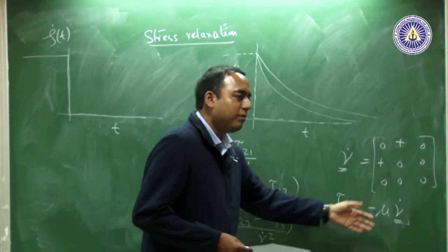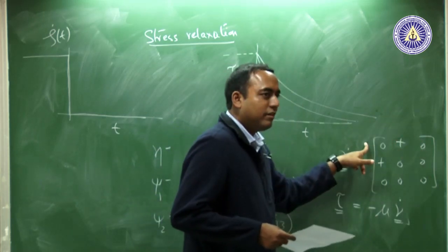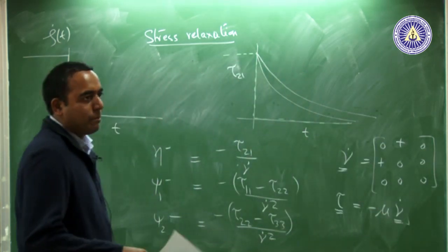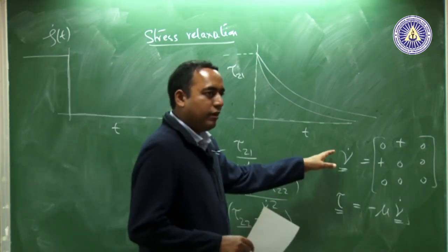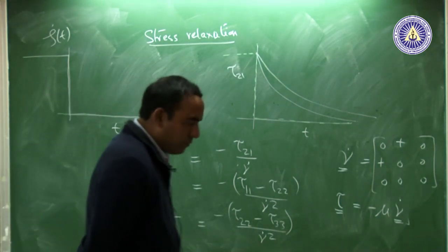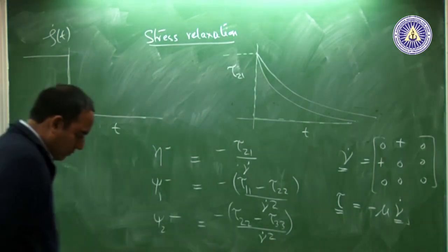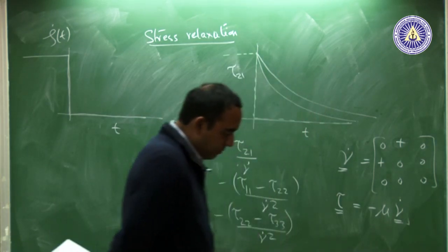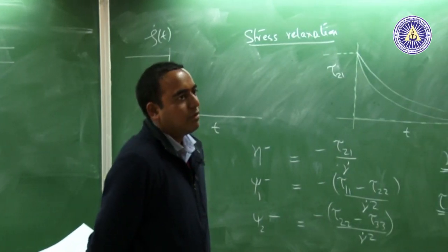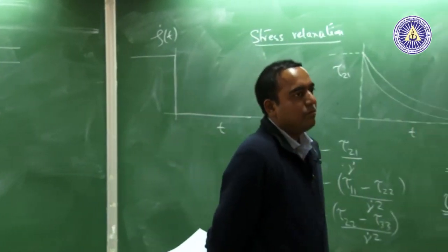See, in Newtonian fluid mechanics, this is the constitutive model that you have, which says that the stress generated is simply proportional to this matrix. But what if it is not simply proportional? So, is it still a function of that matrix? It will be, it has to be. What I am saying is that in these equations I do not distinguish between the 1 and 2 directions, E1 and E2. So, this is a function of this matrix, and also functions of derivatives of the shear rate and all that. So, yeah, there will be more terms than just being a function of this matrix, and that functional form may be complicated.